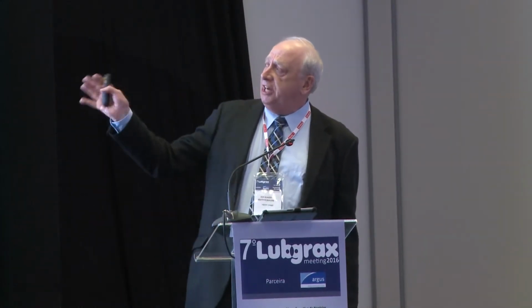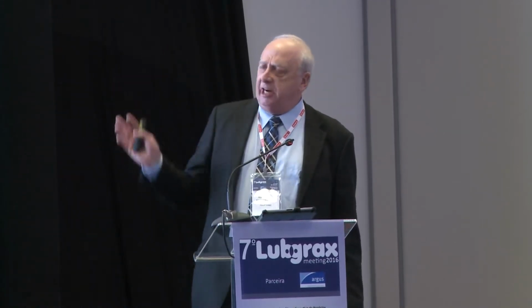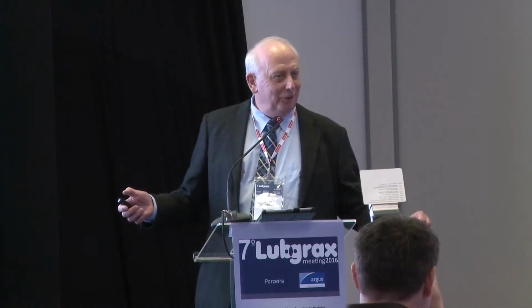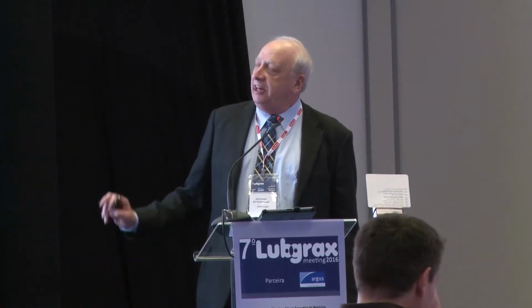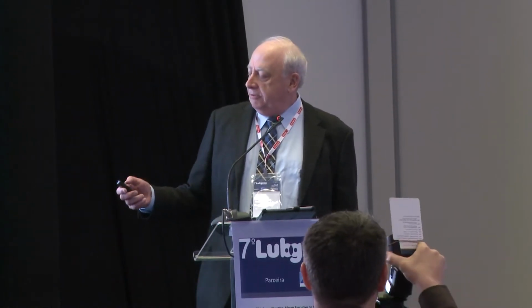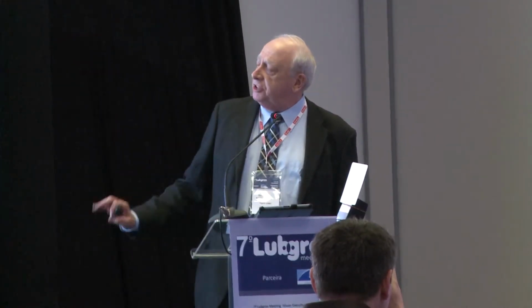If we look at the fungi that we find in metalworking fluids, the list is smaller. Fusarium and acremonium are very common, and you also get some yeasts, including things like Candida. Everybody hear me now? And here's some typical photomicrographs. That is Fusarium, very typical canoe-shaped conidia. This is acremonium. See how they form very dense mats, and when this happens in the field in a fluid, that can cause significant problems.